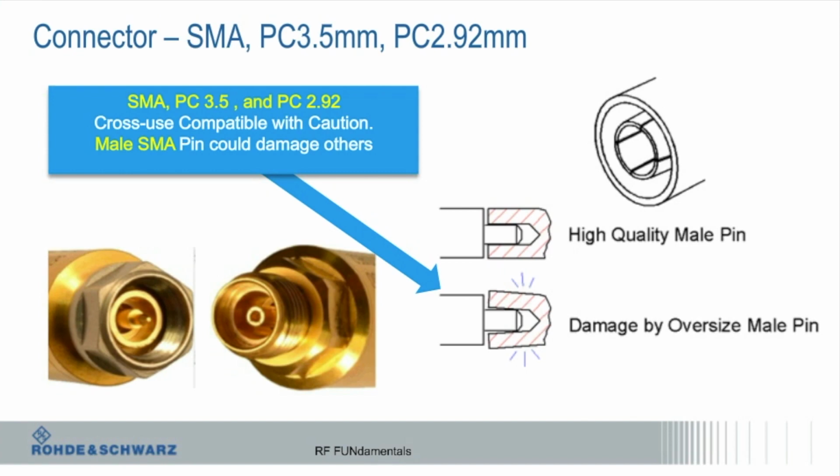And this obviously isn't as repeatable. When you see it's kind of bent like that, every time you connect it, this isn't going to look the same, right? This may be touching down here instead of here, or it may rotate. So if you looked at the VSWR or whatever, it's going to look different every time you reconnect it. So that's why you care. If you use a good connector, that mating surface is going to be along the entire threaded portion right up into where they butt together.